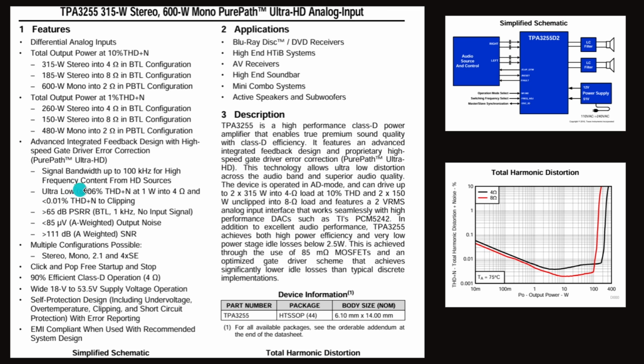Also, those low total harmonic distortions at low volume and at 4 ohms. About output noise, it's good but not excellent. Excellent would be 30 microvolts. Here we have 85 microvolts, but still for most cases those are very good, and generally all parameters are so good. Yeah, those are far better than integrated amplifiers, expensive integrated amplifiers from the 80s and 90s.